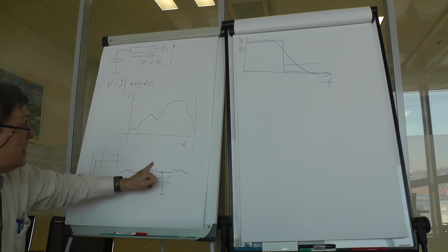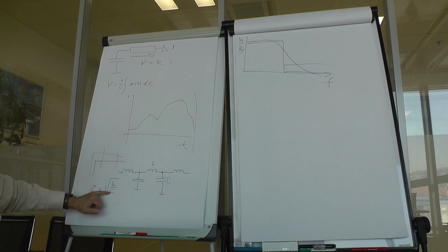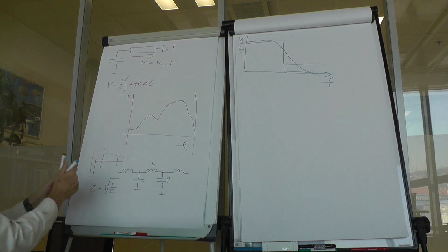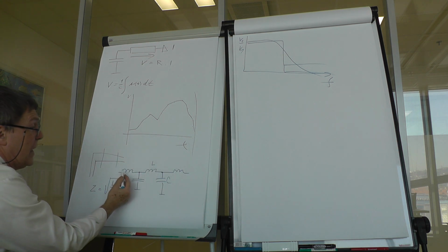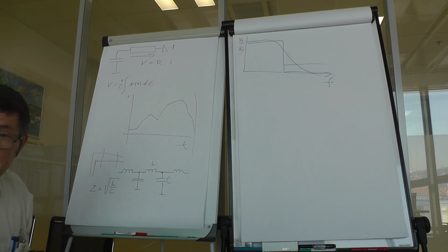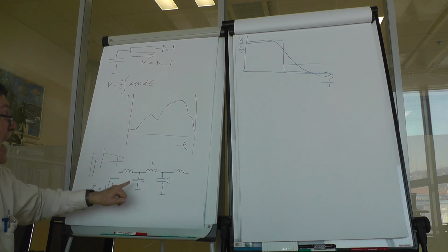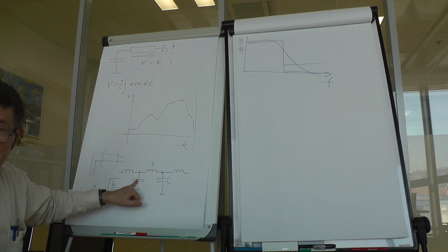So, still the ratio between the inductance and capacitance would be kept if you just take shorter and shorter pieces of the line, but you would increase the number of state variables, that is, the currents within inductors and voltages over capacitors.